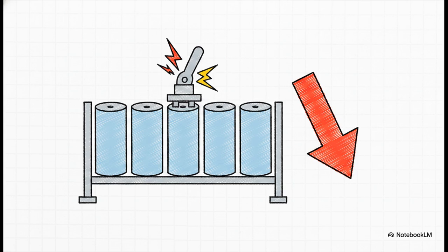Well, the most likely culprit? Your capacitor bank tripped offline. Whether it was a blown fuse or maybe a protective relay opened up, the plant suddenly lost all of its reactive power support. Without those capacitors doing their job, the utility had to instantly step right back in and supply all that reactive overhead again. And that causes the power factor to absolutely tank. This is a very real, very common troubleshooting pattern you're definitely going to see out in the field.